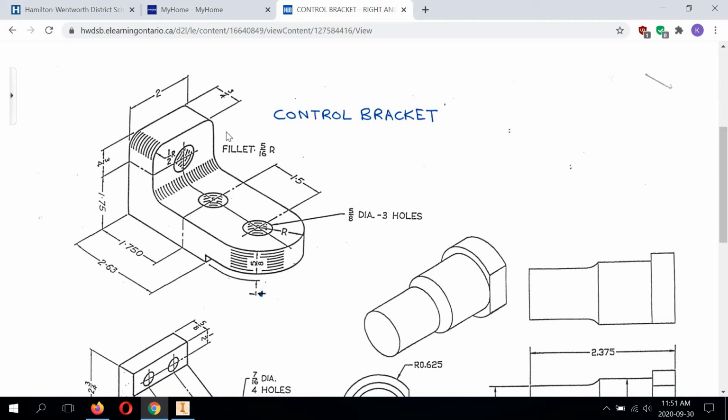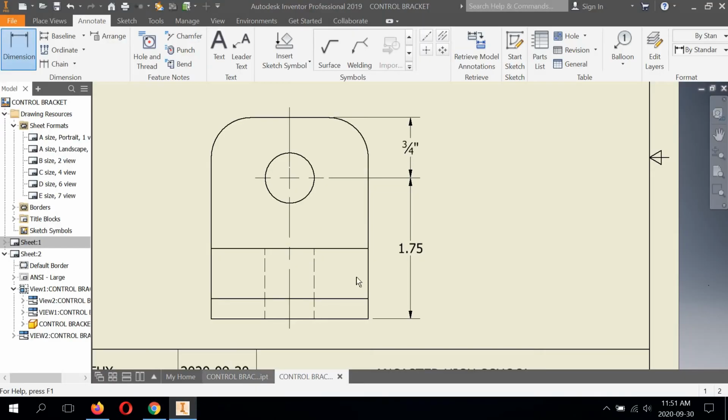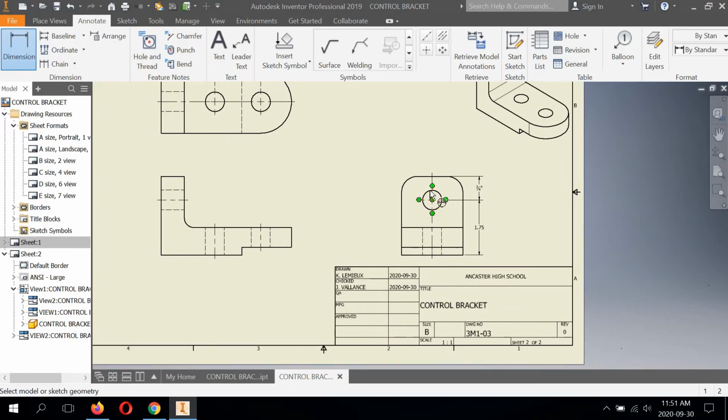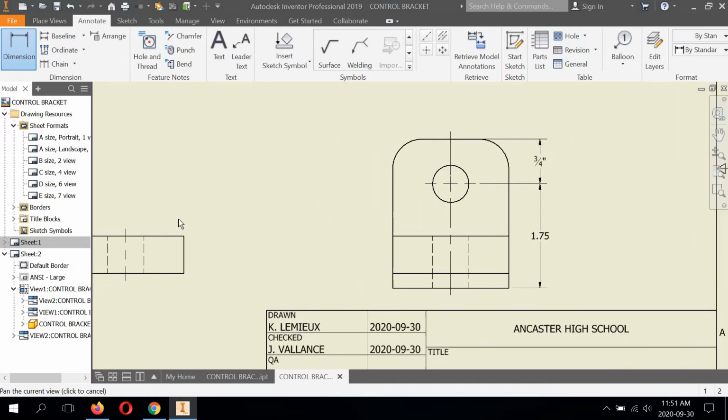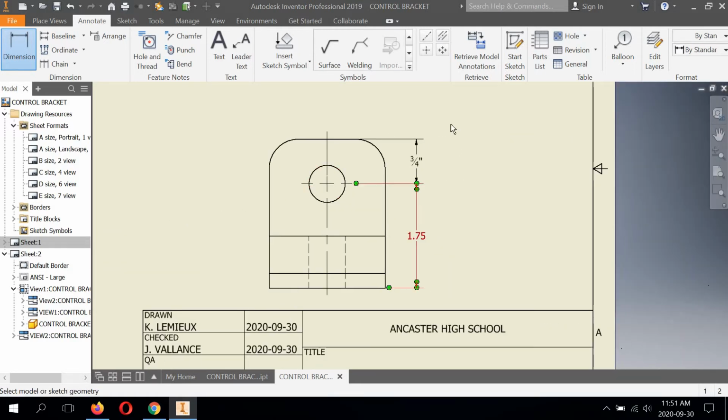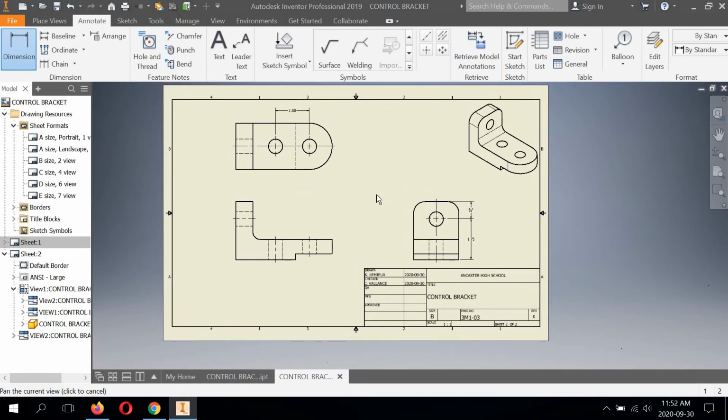Now the reason I have mine over on the right is because it's a good idea not to put dimensions between two views if possible. So if this is going to look exactly the same on the left side and it crowds two views, I might as well clean it up and keep it to the outside on the right where it doesn't crowd anything. This is something we're going to talk more about later, but I'm going to discuss some of my dimensioning styles as I go through this to help you learn how to do this. So that takes care of that one.